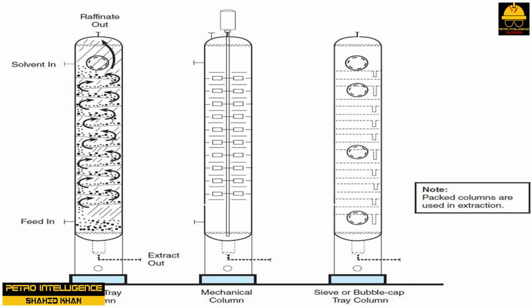A bubble cap tray should perform similarly. A baffle tray is a device for breaking up the countercurrent flows to provide mixing. Baffle trays could take the form of disc and donut trays or crossflow trays. Obviously, contacting is less efficient with such an arrangement, but it is simpler and less susceptible to plugging than our sieve and bubble cap trays.